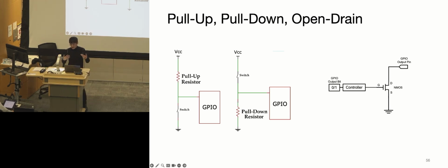So instead of drawing a lot of power from the microcontroller, they have an additional pull-up or pull-down circuit, or connect to additional power that supplies power to those peripherals. That's what the open drain is used for most of the time. Sometimes they also use it to protect the connected device in case it accidentally breaks. But yeah, any other questions?